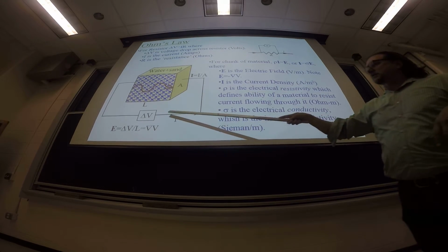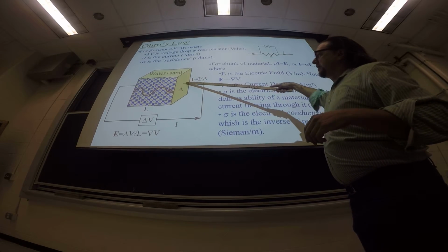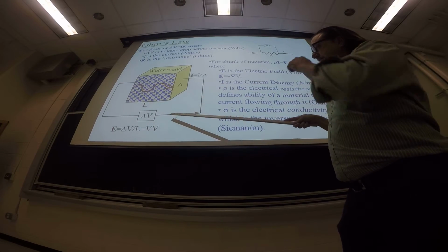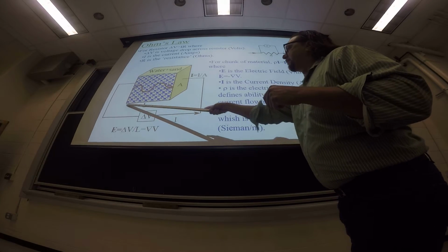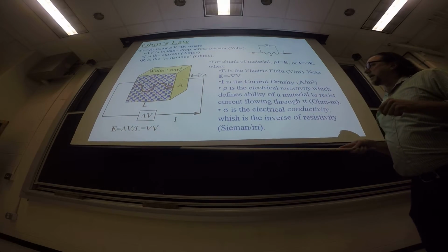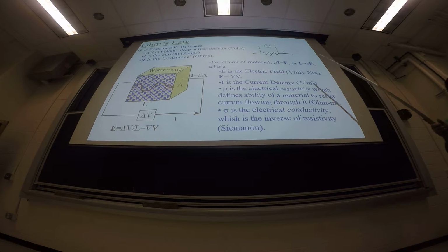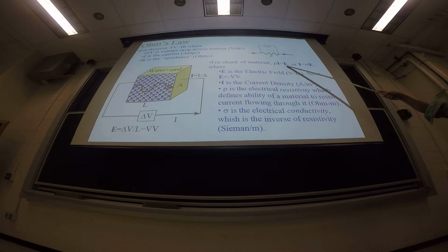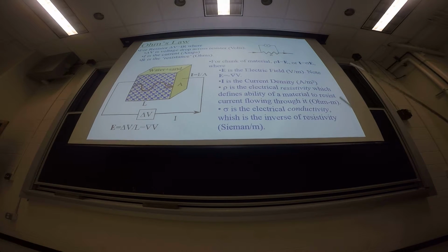And so then we inject a current, just like we did before, so the current's flowing here. It flows through this side of the block with this area A, or it flows in this direction, I guess. And then that block has a length L in the direction that the current's flowing. And it turns out then that you can calculate what's called a volumetric form of Ohm's law, which is given by this expression right here, where rho is what's known as resistivity, okay?